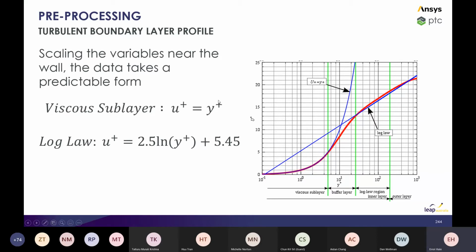Okay, so our position in the boundary layer can be represented by a value called our Y+. And you can see here that our viscous sublayer is a Y+ value of between 0 and about 5. Our buffer layer is between 5 and about 30. And our log law layer is 30 to about 500. In here it's 100, 200, but goes up to about 300 to 500.